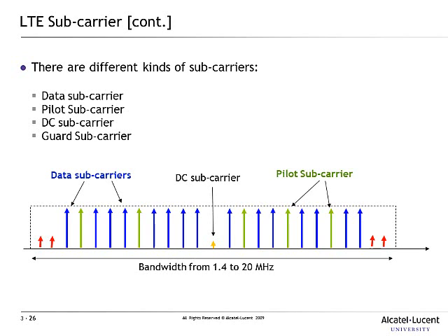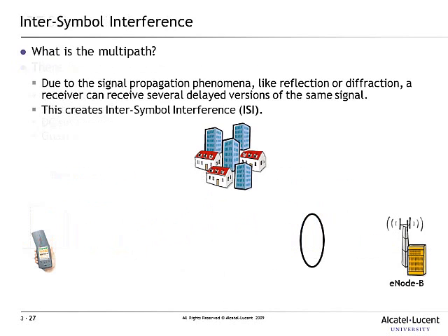And you also have other subcarriers. Some of the subcarriers you may have are guard subcarriers. Another problem that we have in OFDMA is intersymbol interference. Now, interchannel interference means interference between one channel and the other channel. Intersymbol interference refers to transmission from one UE, because you've got to transmit one symbol, then you've got to transmit the next symbol, and so forth.